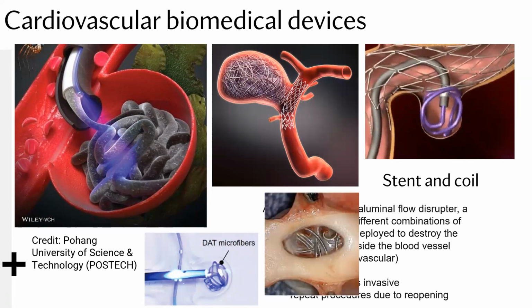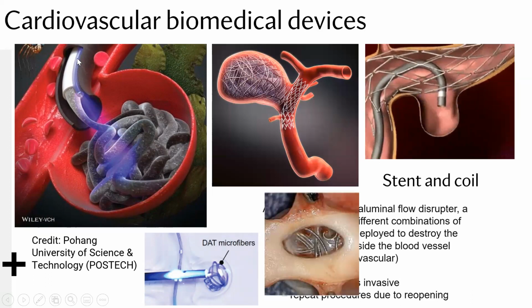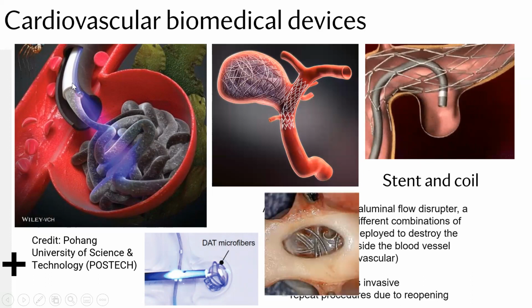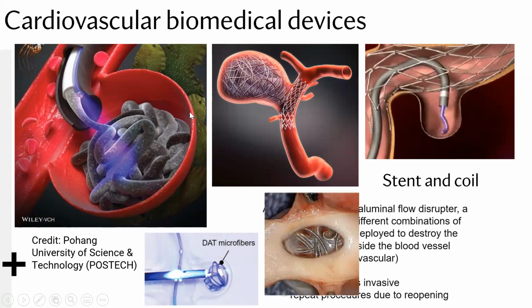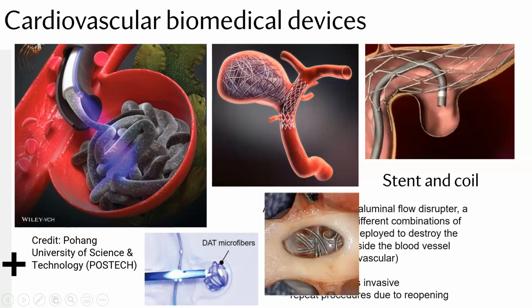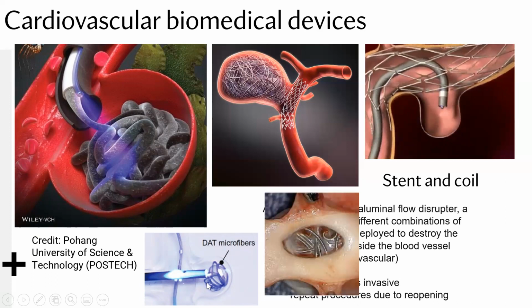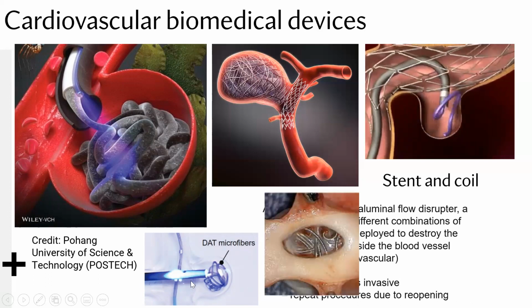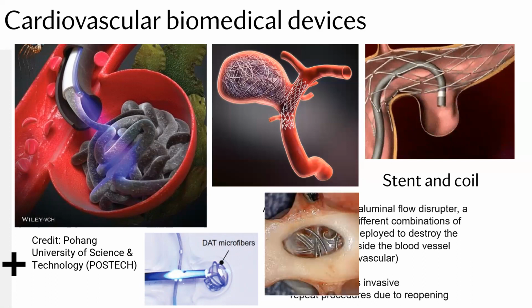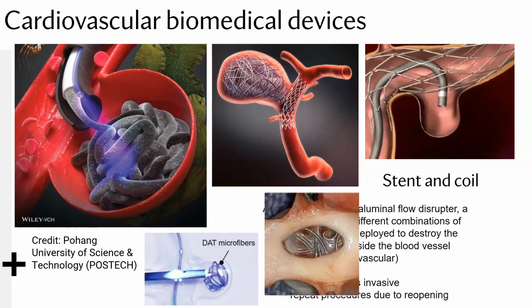And it's a very clever design of this exposure probe here that actually cures the material in place as it's being added. So here you can see, for example, the microfibers are injected, and then the UV light is curing them into place to cross-link the material in place.